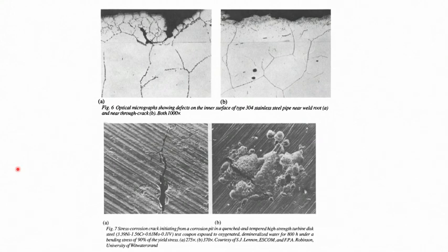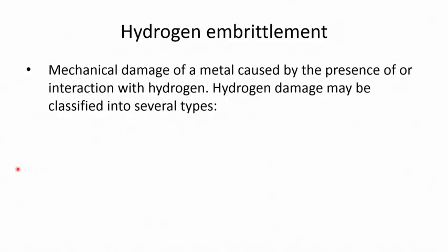So, if you think of mitigation of the stress corrosion cracking problem, the best way to minimize the probability of stress corrosion cracking is by choosing proper material for the proper environment. The second way to get rid of this problem is by reducing the stress level of the material, particularly the internal stress present in the component. And of course, by the application of inhibitors you can reduce the aggressiveness of the environment. By the application of cathodic protection you can also reduce the stress corrosion cracking tendency to a large extent.